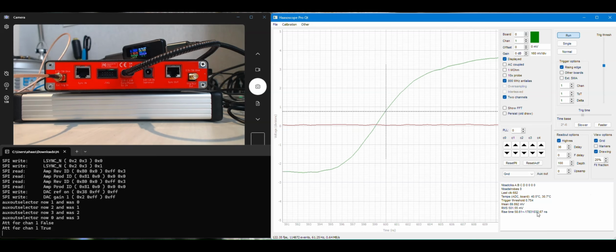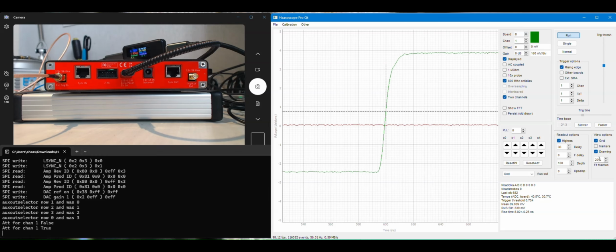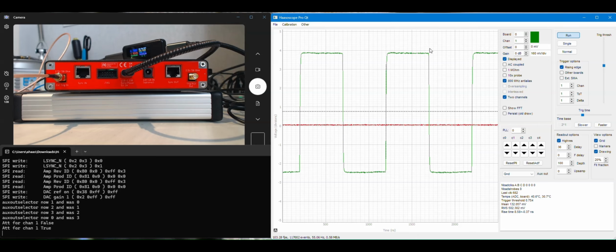You see when we zoomed in here, it kind of goes wacky and it doesn't know what's going on and is failing. That's because of this fit fraction thing. So this fit fraction is telling the program what fraction of the visible area to use to actually do the fit, and right now it's set to 20%, so it's only using 20% of the area that's visible centered around the trigger point to do that fit, because sometimes you might have multiple signals going up and down, so what do you fit for rise time?